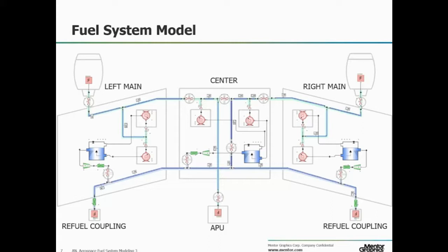The thin link lines represent a direct connection between adjacent components and are not pipes themselves. Nodes sit in the middle of the links and serve as convenient points to enter elevation data and interrogate flow results of temperature and total pressure. We took a more detailed look at the arrangement of the pipes, pumps, valves, and tanks in the first two presentations. For a more thorough explanation of the base model, you can re-watch those earlier presentations.